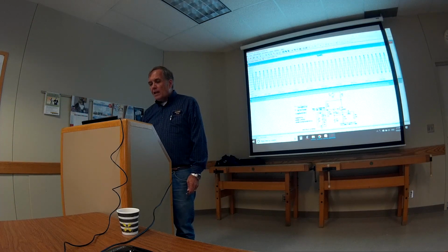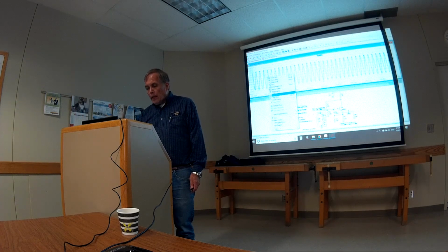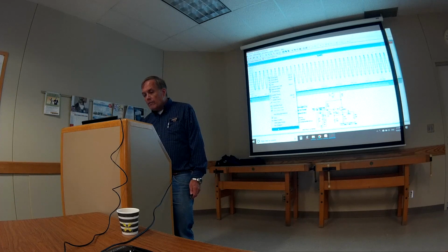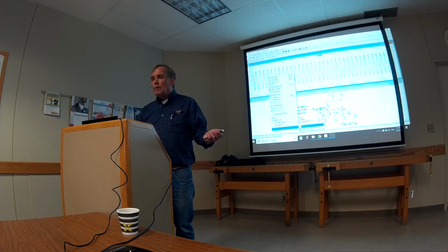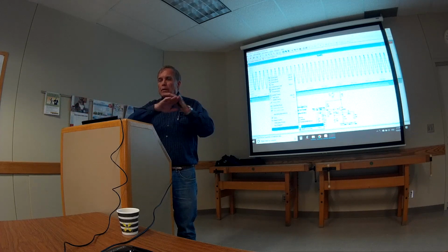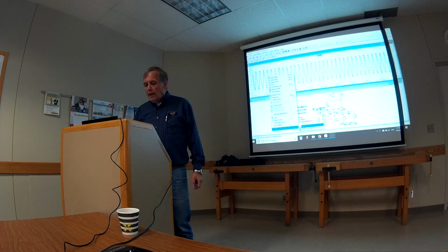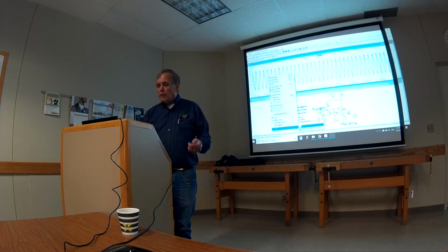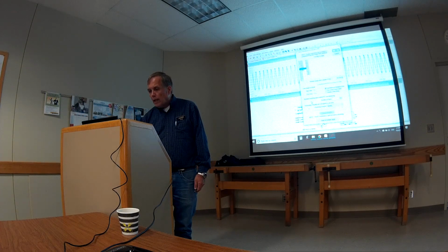LTspice has a very cool thing. You go into the waveform, right-click, go down to the very bottom, and it says View, and then FFT. You know what an FFT is? Fast Fourier transform. That's like a spectrum analyzer view. Now you're changing from the time domain to the frequency domain. In other words, the bottom axis is going to be frequency instead of milliseconds. This does a fast Fourier transform as a shortcut to make it modelable. Otherwise, it's too complex. But it's a quick way of making a spectrum analyzer view.